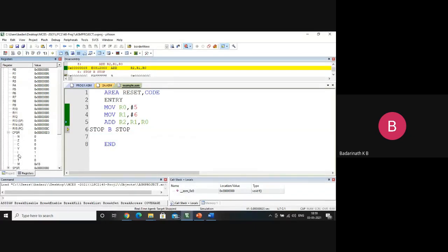Look at that CPSR. CPSR contains four pieces of information. One is M. M is what? The mode in which it is running. It indicates the mode by a number, which is represented by 5 bits. Then there is Thumb, T is 0. That means I am not in the Thumb mode now. Then I and F represent enabling or disabling of the interrupts, which is 1. Interrupts are enabled. Now, the other use of CPSR is the flags.